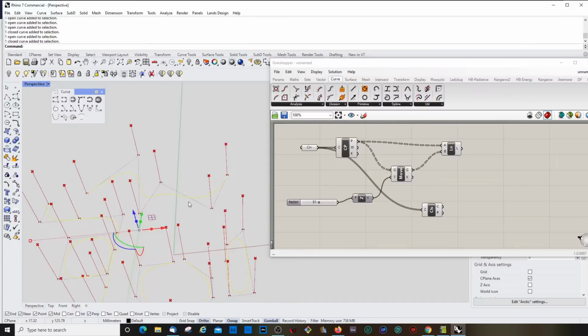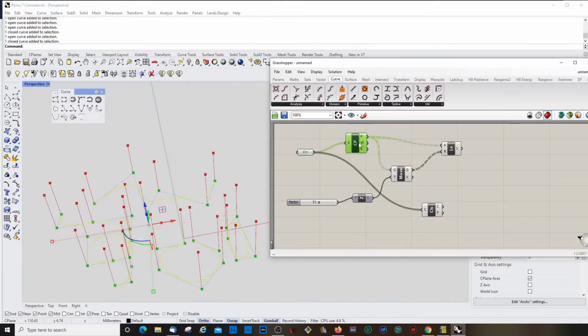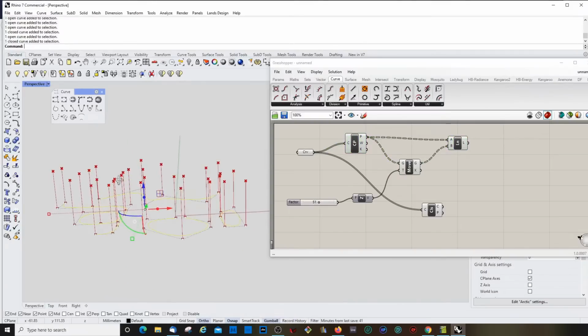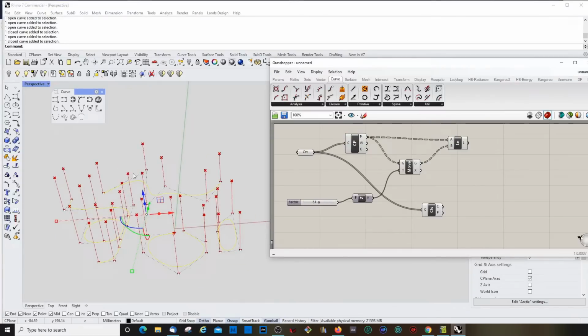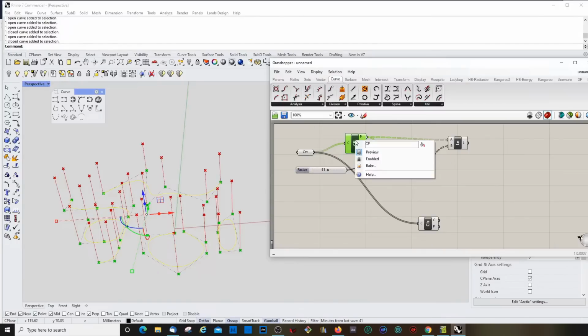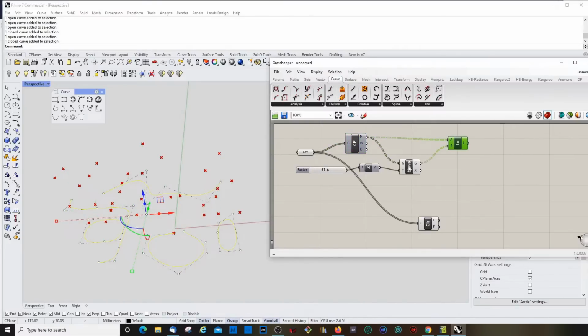Now you're shocked. So it also uses this portion of the script to create all these vertical points, all these vertical lines. If I don't want to see that at the moment, because I'm actually looking at open and closed curves, then I can go here and right click and say close preview, and now this is closed.